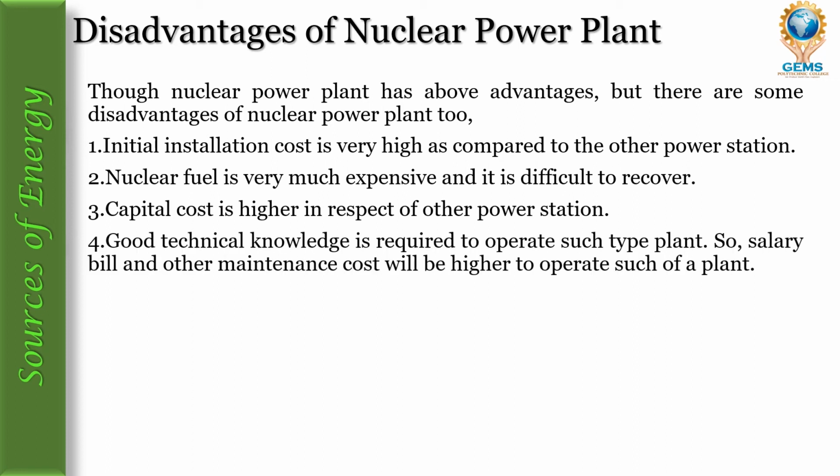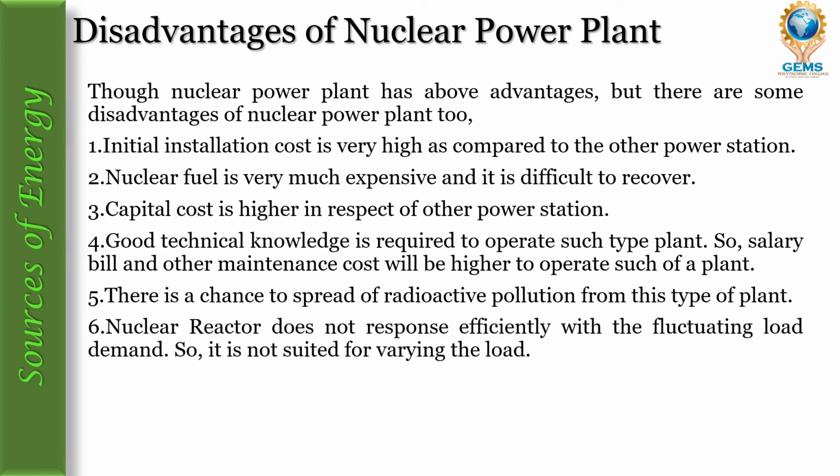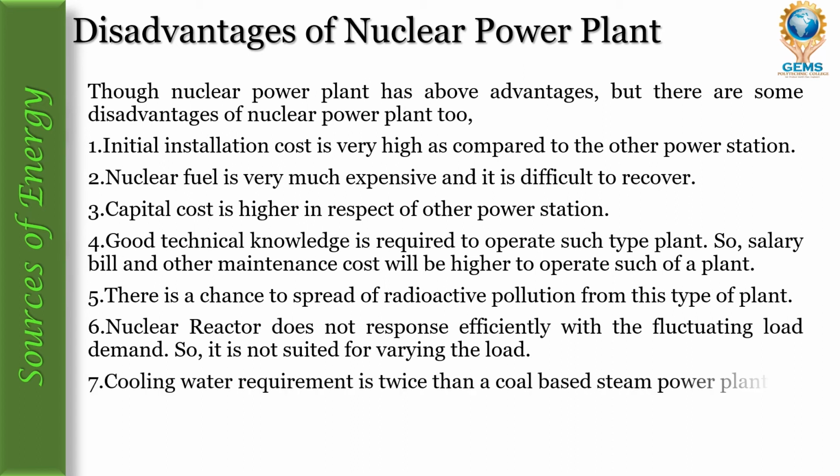Good technical knowledge is required to operate this type of plant. So salary bill and other maintenance cost will be higher to operate such a plant. There is a chance of spread of radioactive pollution from this type of plant. Nuclear reactor does not respond efficiently with the fluctuating load demand, so it is not suited for varying the load. Cooling water requirement is twice that of a coal-based plant.